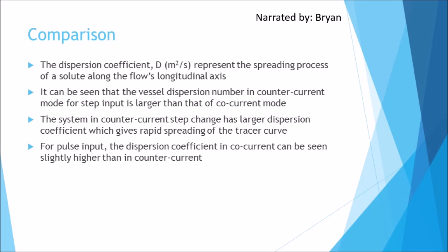From the comparison above, it can be seen that the vessel dispersion number in countercurrent mode for step input is larger than co-current mode. This means that the system in countercurrent step change has a larger dispersion coefficient, which gives rapid spreading of the tracer curve.